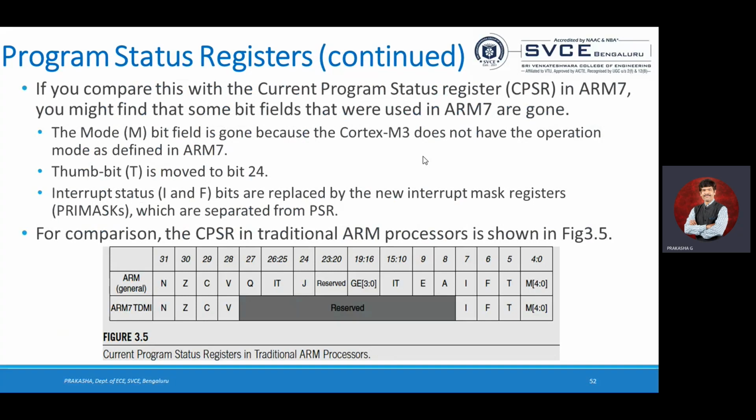In that one, a set of registers is going to be used. In user mode, almost all the registers we are going to use there: R0 to R15, CPSR, stack pointer, link register, and also program counter, everything you are using over there. System mode and user mode are both similar, but we are just checking it out. The mode bit just shows whether it's user mode or system mode, which mode you are using. Based on the mode, the program is going to execute. User mode or system mode.